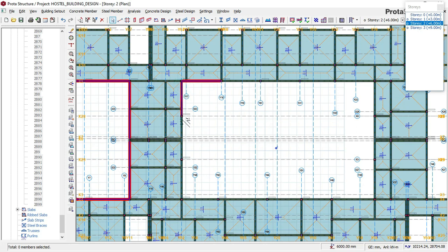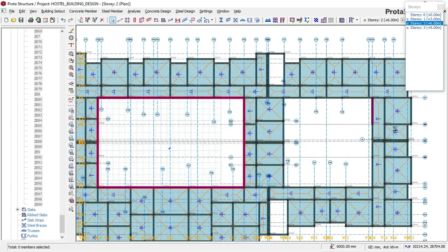So you have to take off all the wall load around the perimeter for the courtyard if you're using this particular file. But if you're not using this file, then you don't need to take off these perimeter beams. That's why I say you need the CAD file to be able to see what is happening in this area, because this area does not have a wall load in the CAD file. So on the CAD file, you'll be able to see and validate what we are doing. You can get the CAD file from the link down below. Okay, and then we move to the next one here.